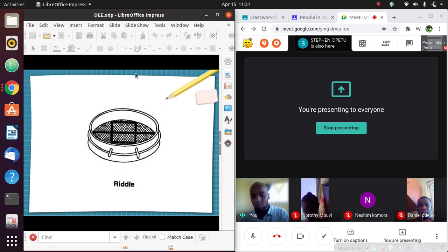The first few layers of sand that you put in can be rough, but once you go to fill the box, you use a riddle, or sieve, so that you can filter out the sand. You won't find large particles, so that the sand that fills the top part of the box is fine. You use that to filter out the big lumps of sand, so that the sand that falls into the box is fine.